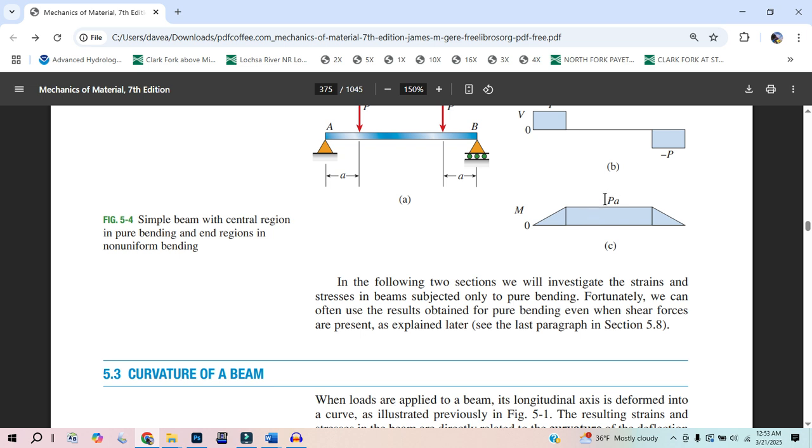And if it failed in shear, our models show that a little square diagonally turns into a diamond where these two points get farther away and it's getting ripped apart. So it actually gets ripped apart in the middle. So failure in compression can be failure in shear, which is failure in tension.